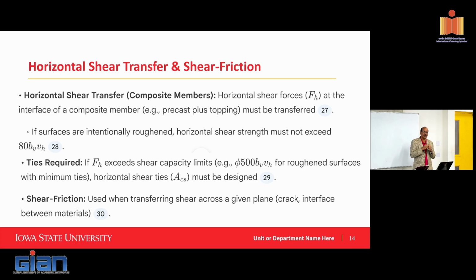I think we saw in one of the slides, you have loop rebars come together and you pour concrete. Those are intended for making them monolithic. But when the crack opens up, the crack tends to find the weaker region, typically closer to where the interface originally was.